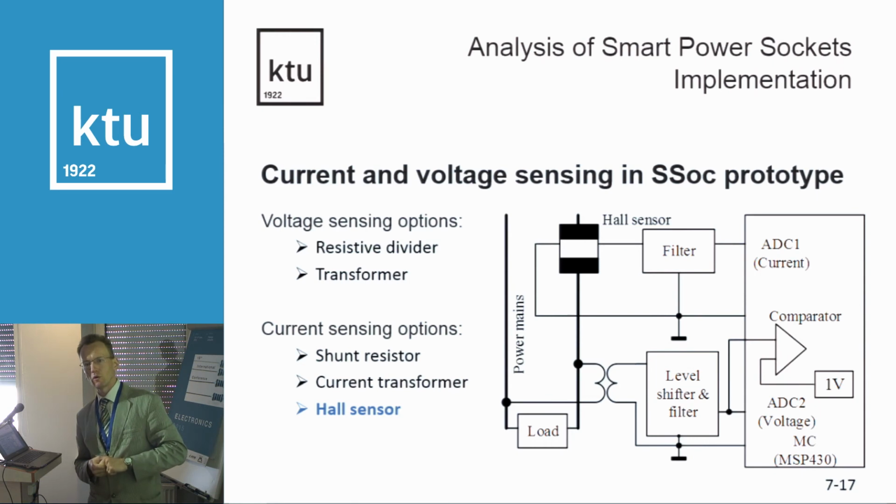They are both connected to separate channels of the analog to digital converter with the appropriate filtering and level shifting, from analog preconditioning of the signals before they are sampled and discretized. Quite often the microcontroller used is the MSP430 from Texas Instruments.